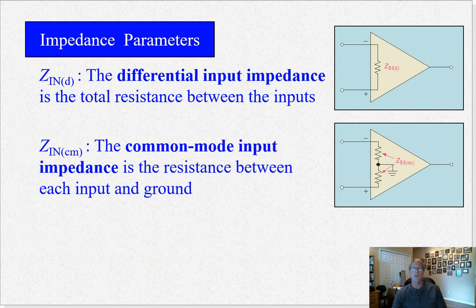What you have to do is measure the current going into these and then take a voltage measurement and do Ohm's law. All right, or use a potentiometer where you dial in the value, and when one of the terminals becomes half of the source voltage, you know that the series resistance in that potentiometer equals this resistance. We'll look at that in our lab, and you'll understand more about how that works. But for now, just understand you cannot just take an ohm meter and measure these directly. You have to do it indirectly.